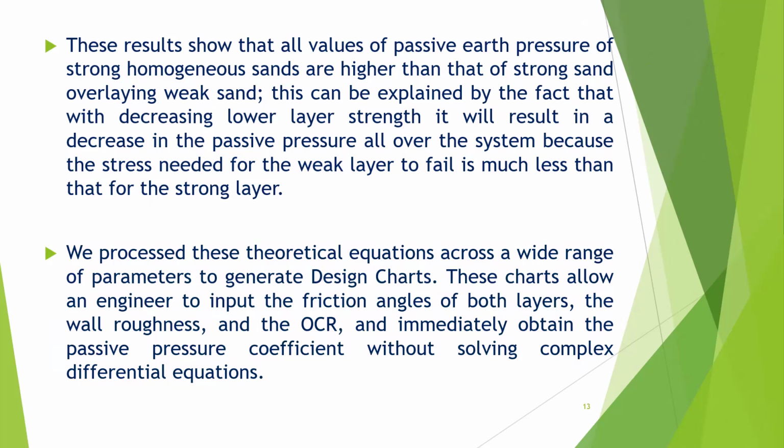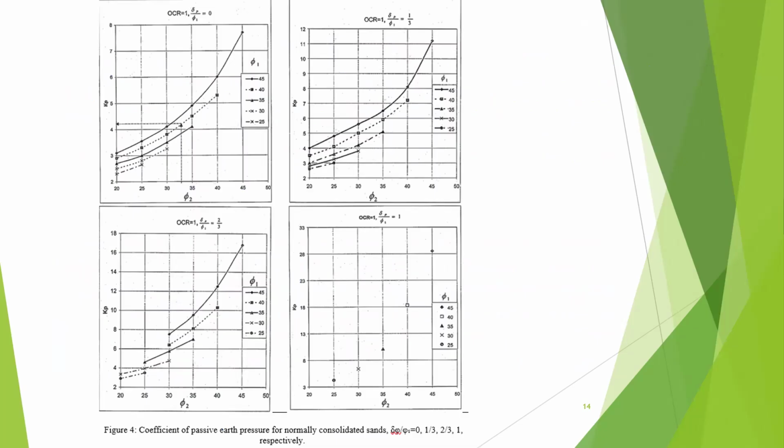We process these theoretical equations across a wide range of parameters to generate design charts. These charts allow an engineer to input the friction angle of both layers, the wall roughness, and the OCR, and immediately obtain the passive pressure coefficient without solving complex differential equations. In this figure,